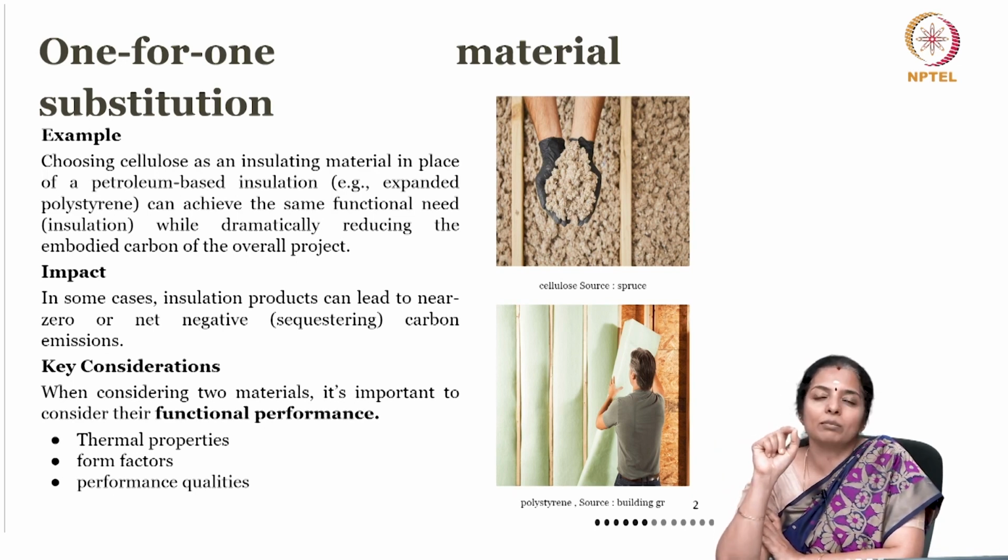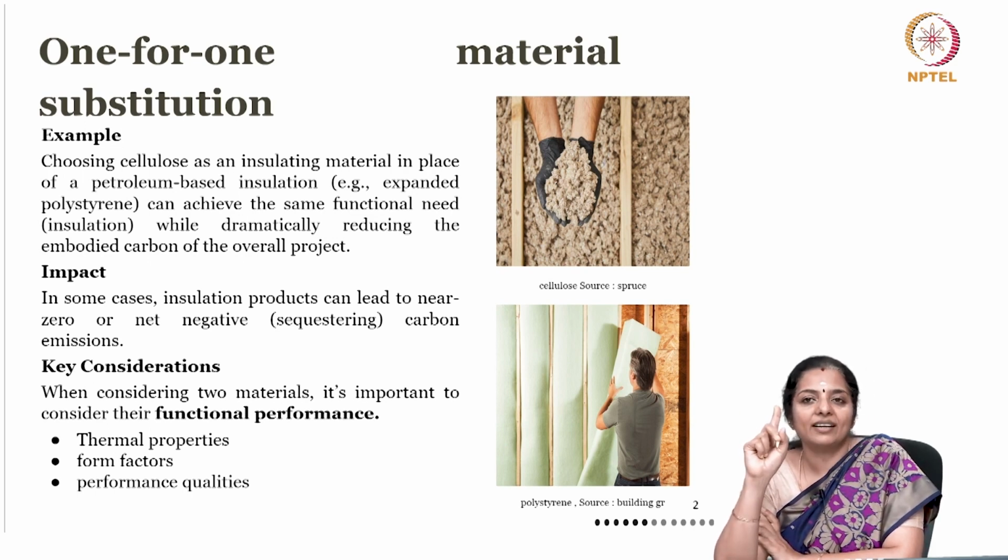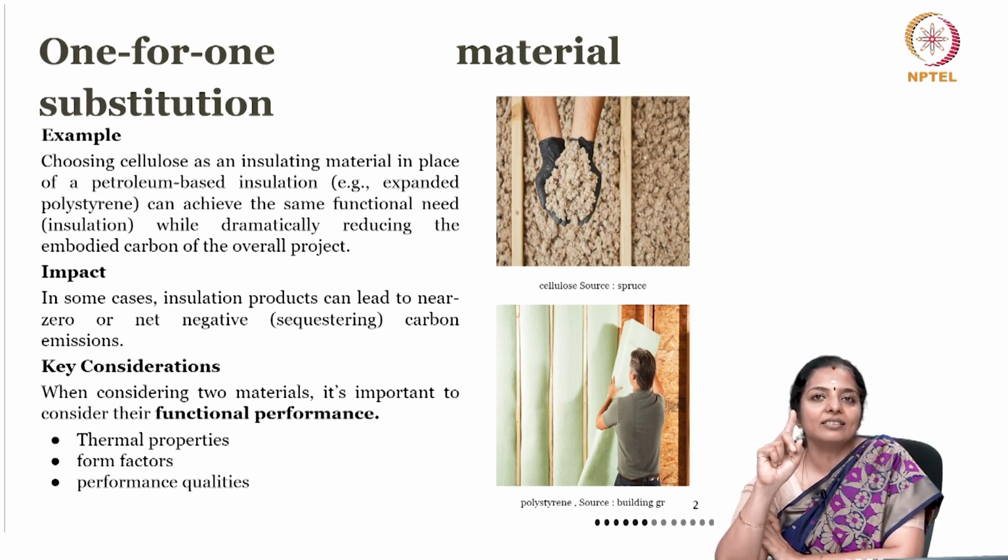So choose that, because that slide was for achieving the same U value. So for achieving the same functional end, consider the choice of building material. Substitute one material for another, a carbon negative or at least low carbon material, to achieve the same impact that you want.